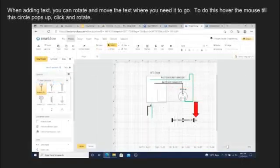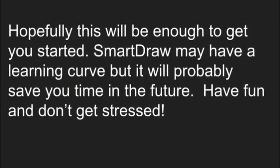When adding text, you can rotate and move the text where you need it to go. To do this, hover the mouse till this circle pops up, click, and rotate. Hopefully this will be enough to get you started. SmartDraw may have a learning curve, but it will probably save you time in the future. Have fun, and don't get stressed.